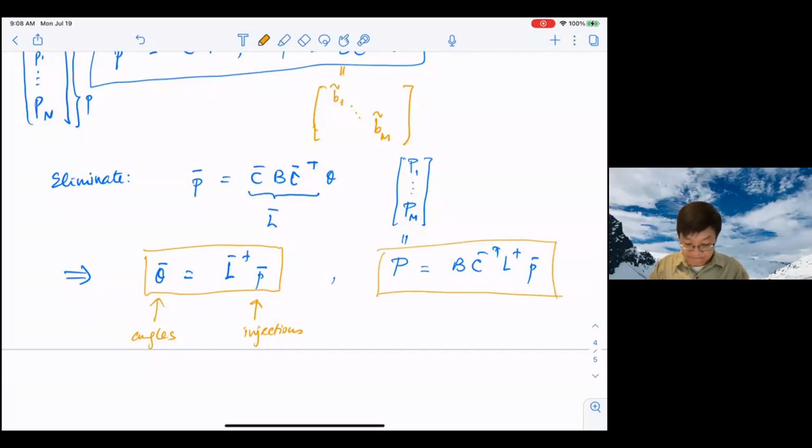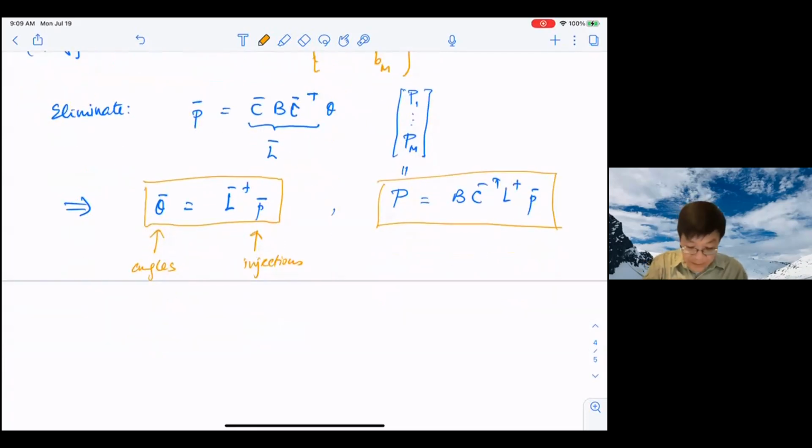Okay, so the Laplacian matrix is n+1 by n+1, but assuming the network is connected, it only has rank n, which means it's not invertible, and the null space is only the span of the vector 1. The implication of that is that the angles theta on the network are determined only up to an arbitrary reference angle. It doesn't matter what the reference angle is, it will not affect the line flows in the network. Right?